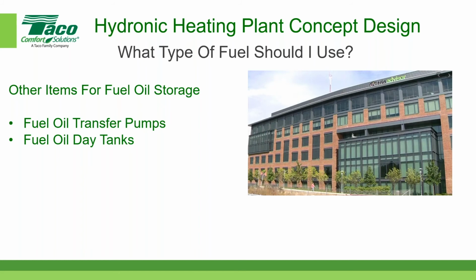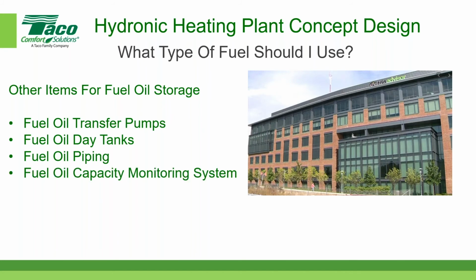So you need to have fuel oil day tanks. You also have to have fuel oil piping, and you need a fuel oil capacity monitoring system that tells you how much fuel oil is in your storage tanks. And the other thing you need to have is a fuel oil leak detection system. So fuel oil has its complexities. Even though the fuel has a higher heating value than natural gas, it also has its storage and transfer complexities and monitoring complexities. And all of these systems have to be incorporated for a fuel oil storage system.